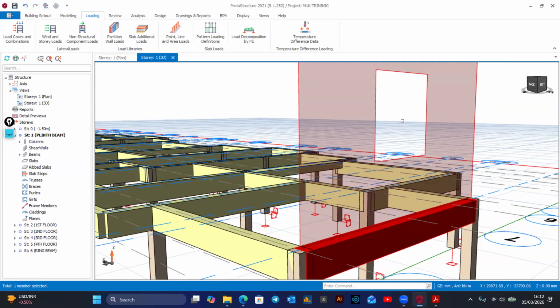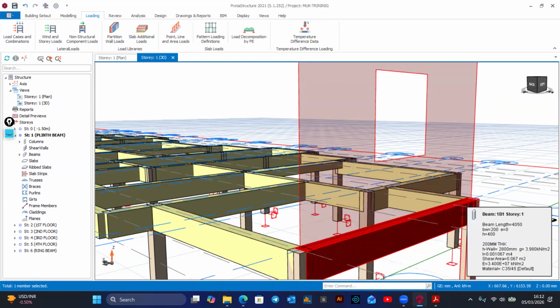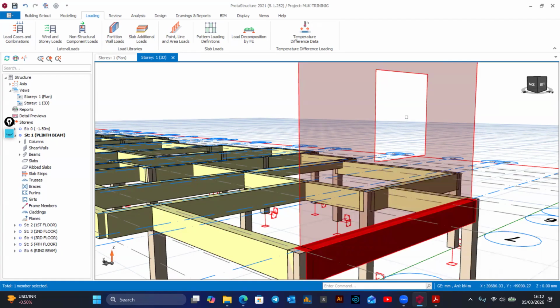If it is your house that you are designing, you can do it that way. But if it is for another client, don't include those openings because you don't know. The moment you include this opening, you're telling us that the weight of this beam doesn't include this opening, but you're going to fit a window there, which also has a weight.